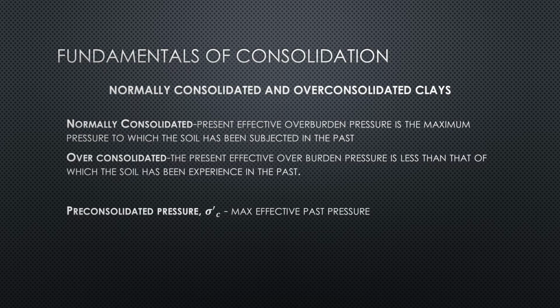The present is the overburden pressure being applied. If you say overburden, it is the pressure applied on the soil. In our case, that will be the structure, the foundation. If you apply the overburden pressure on the soil, if we say normally consolidated, the overburden pressure we apply is equal to the maximum pressure the soil has experienced.